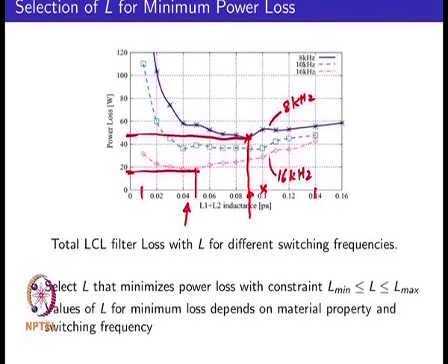So, from multiple perspectives, you can end up with a better filter by doing a close analysis of the power loss and the thermal rise in your filter.